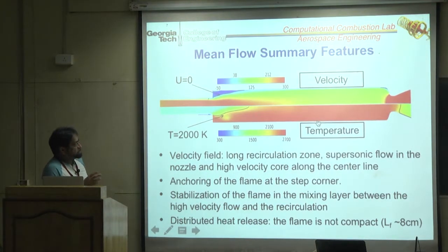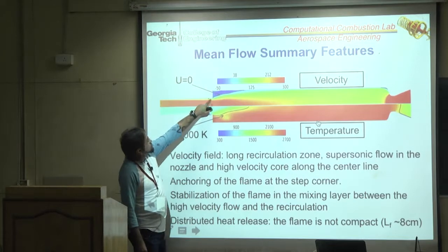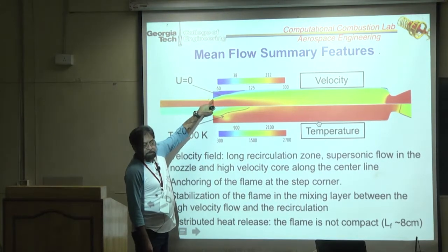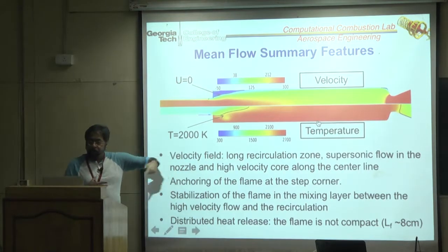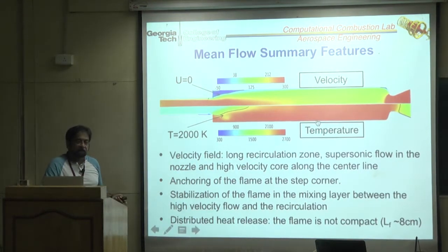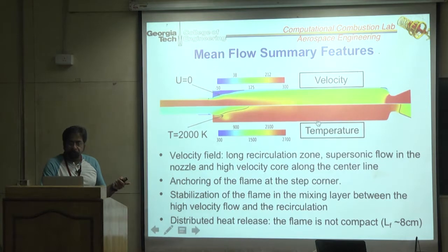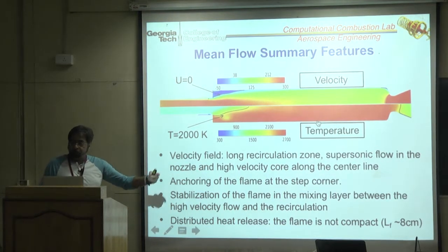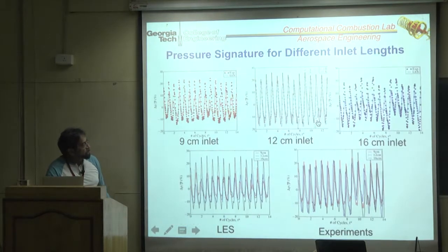So it is a non-premixed system with an anchoring mechanism that is by rich premix. It's not even stoichiometric premix, it's rich premix, because there's a lot of fuel here. So that means that later on it's going to burn. A rich premix means that there's fuel left over after it's anchored, after it is burned. So that fuel is going to mix again and burn, so you get a very complicated structure.